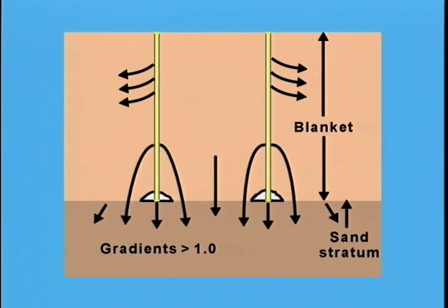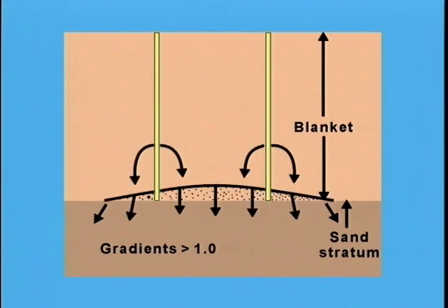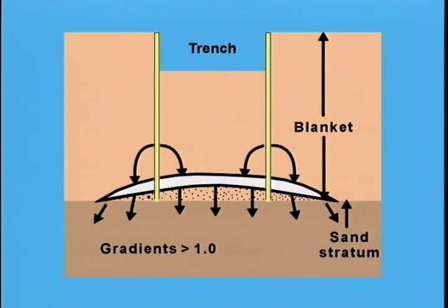Material is first lost from the bottom of the blanket adjacent to the bottom of the cracks. In the upper part of the crack, water is seeping into the blanket. This seepage stabilizes the sides of the upper part of the crack. At the bottom, where material is lost, the minus number 200 fraction of the blanket is washed into the voids of the outwash sand. The plus 200 fraction, which is only a small percentage of the total blanket, is left behind. A void space developed above the plus 200 material and with time works its way toward the surface.